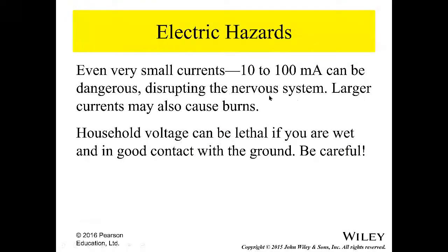Now, electric hazards. In our household circuits, we can have things that draw 10 amps. We can have things that draw only 0.1 amp, 100 milliamps. But nonetheless, they can be dangerous if there is a short somewhere in your circuit. And household voltage can be lethal if you are wet.